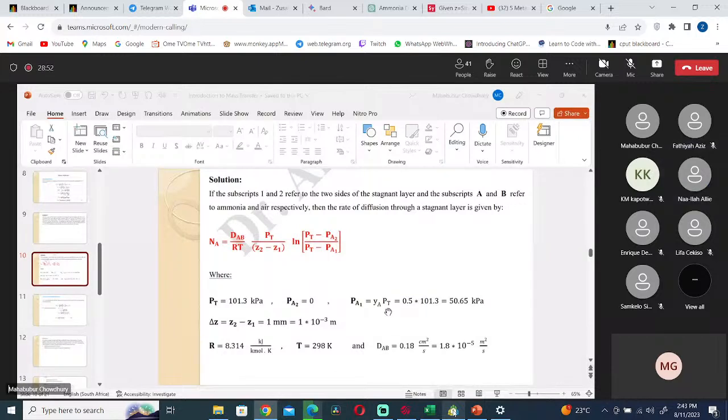What did you plug in for the pressure? What value did you put in? kPa, right? Yeah. Okay, let's see if maybe mine is mistaken, but let somebody else do it. And when you did the thickness, oh, I put in millimeters. Yep. So you need to change it to meter. Okay, so mine is correct. And get me the unit, please.